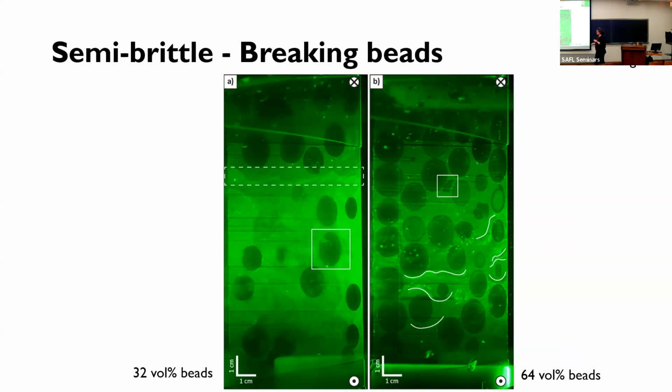And then one thing that we didn't really count on, that just happened to be the case, we can also start seeing the actual viscous deformation in the fluid by having some kind of streamlines that start forming when we continuously shear. This is simply due to sometimes these materials start growing mold if it's not cold enough, and so you can start basically shearing mold. That was not an intentional thing, that just happened, but it was an interesting little piece of evidence to see the viscous deformation in the fluid.